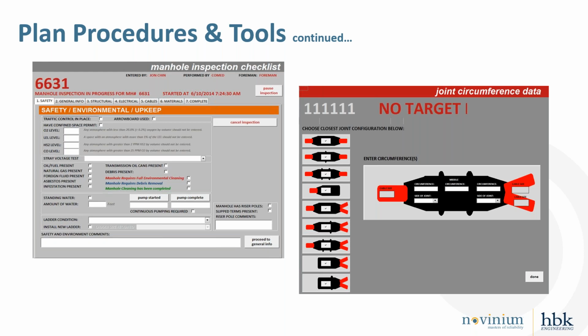The same type of customization can apply to things such as grounding, secondary bus, switches, or transformers. Now, because the data is normalized across all the inspections, a utility has a much greater tool for analyzing the condition of their system and what contributes to those conditions. When evaluating, say, a specific cable jacket type across hundreds of thousands of cable segments inspected, a standards group can make some very good determinations about what factors are leading to the conditions that that type of cable finds itself in.